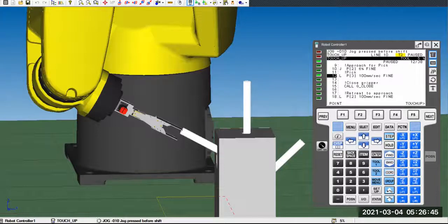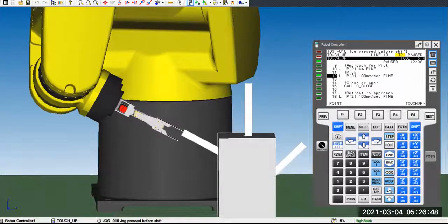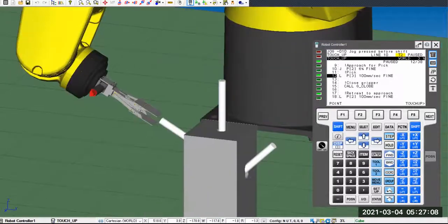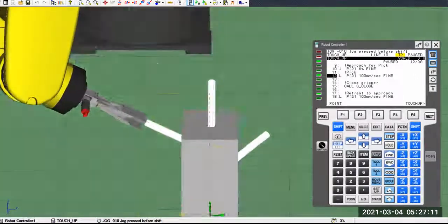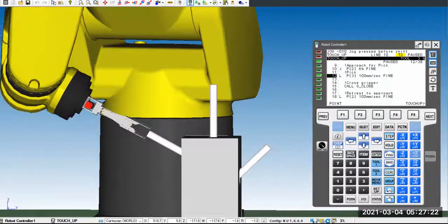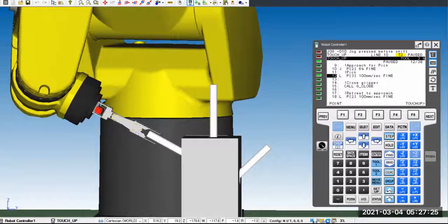So right now it's in two and looks like our gripper is going to collide with the pin. So we need to move straight up a little bit. So we have to switch back to roll. Again, you need to choose the coordinate according to the situation, right? And slow down the speed going to positive Z, right? So in that, let me see here. Yeah, looks like we can go in now. So now, before you go in, you have to switch to 2, positive Z. You go into the pin now, right?